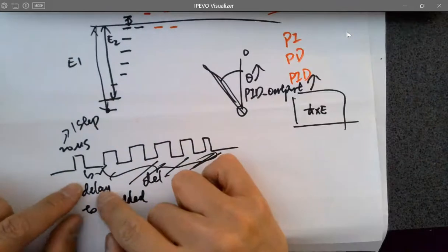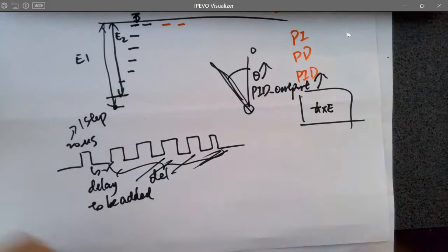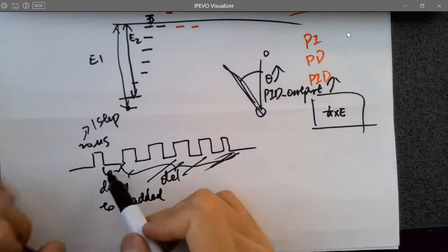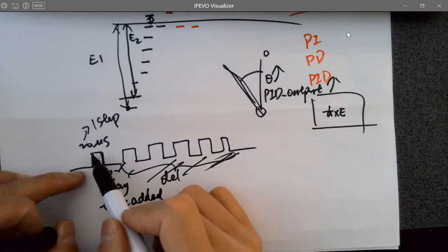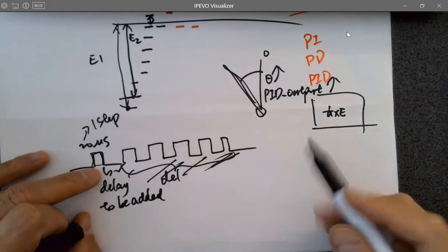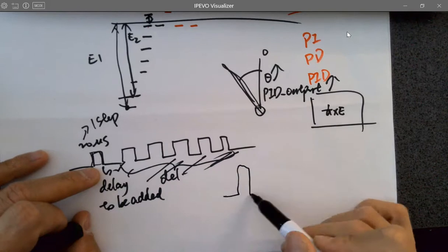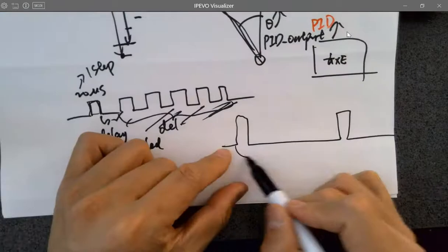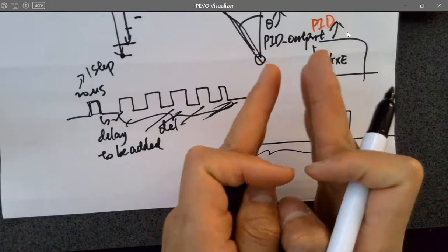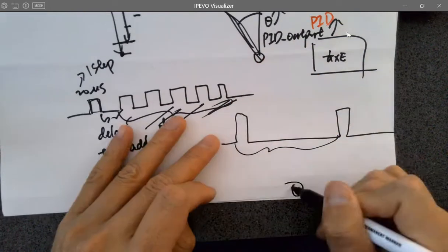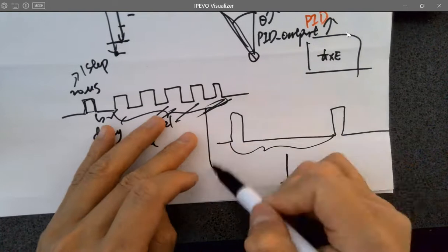You don't want as much delay over here. So you have options. If you make a connection with your probe to the pulse, the step being sent to the stepper motor, to the oscilloscope, you are going to see this with the different duty cycles, right? The duty cycle here will be changed in real time, depending on the angle. So whenever the car is balanced, you are looking at the oscilloscope, what's going to happen?